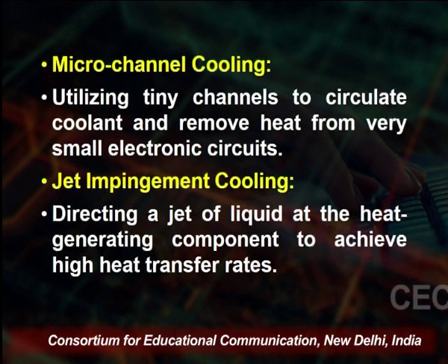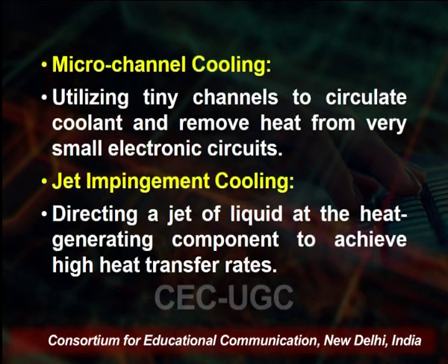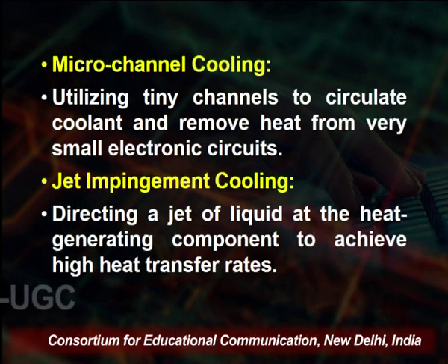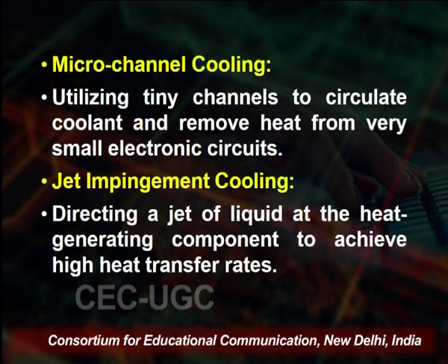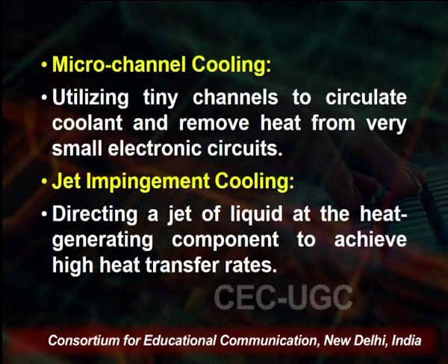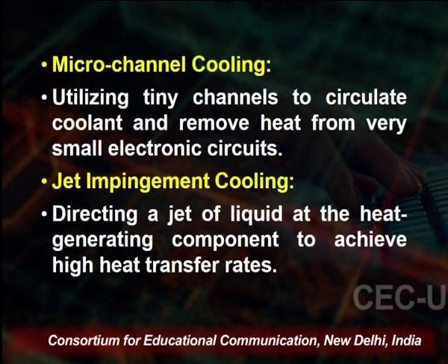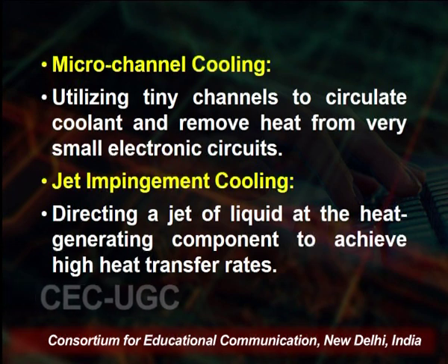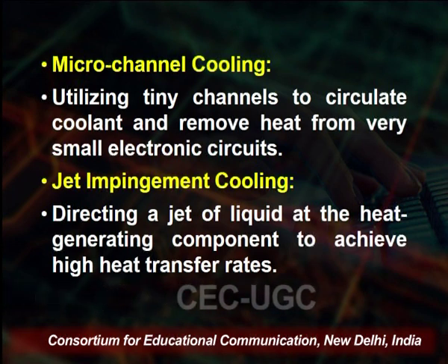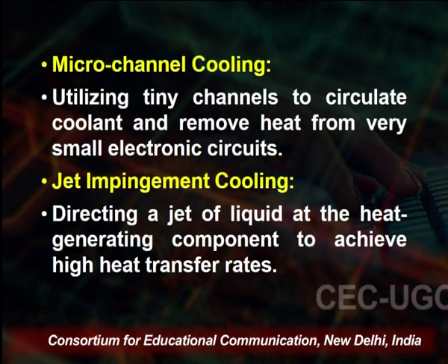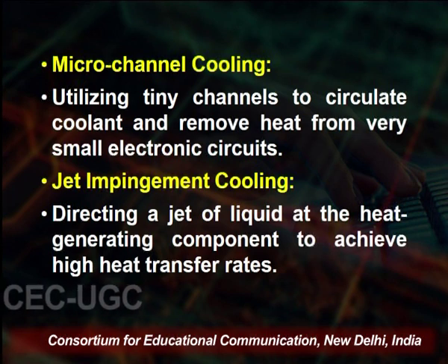Another is microchannel cooling, which utilizes tiny channels to circulate the coolant and remove heat from very small electronic devices. So microchannel cooling is also used in nano devices. Another is jet impingement cooling, directing a jet of liquid at a heat generating component. By using this we can achieve a high heat transfer rate.